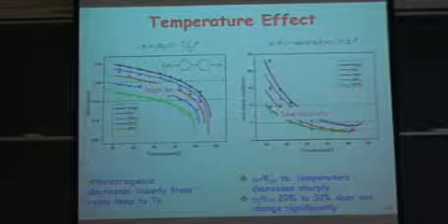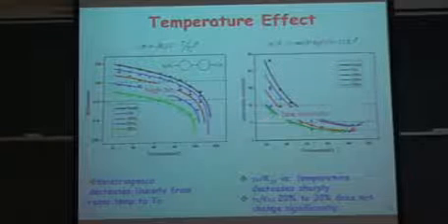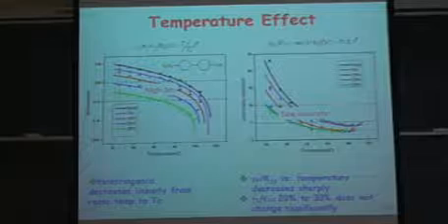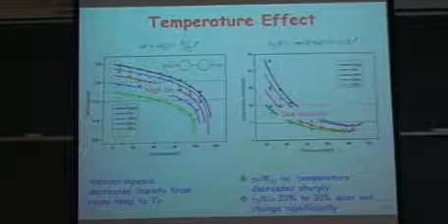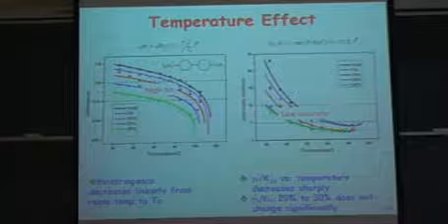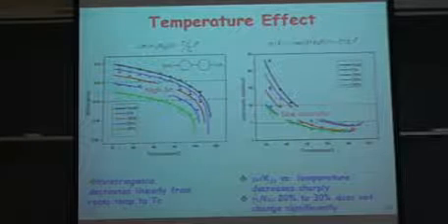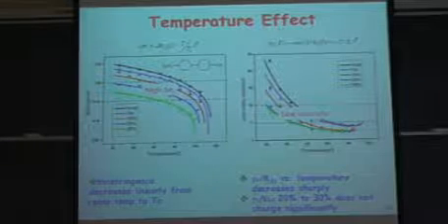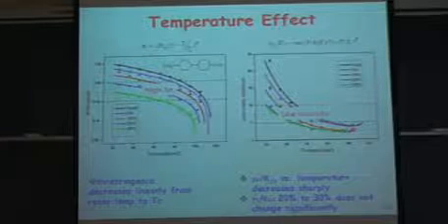We can see 20% and 30% almost overlap with each other. So this tells us one thing: at a certain percentage, the viscosity doesn't increase anymore. So we should not dope more than that. So keep it at around 20%.